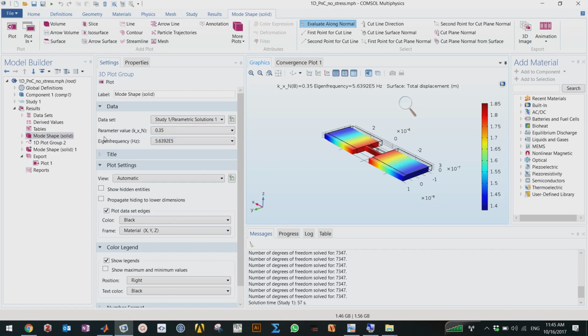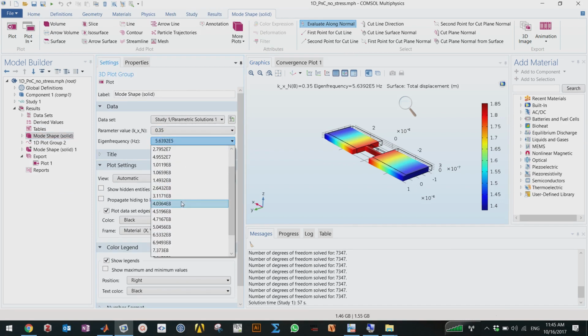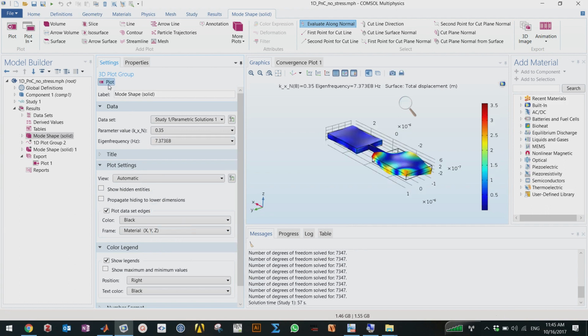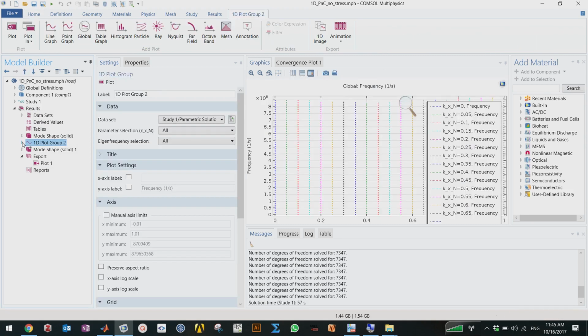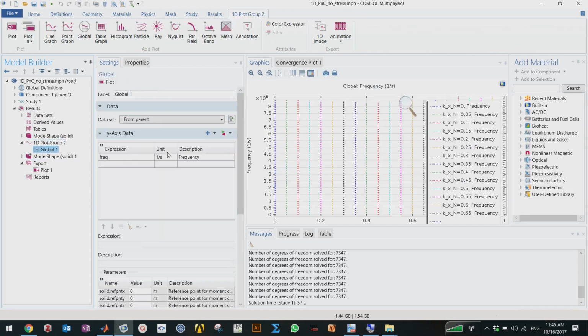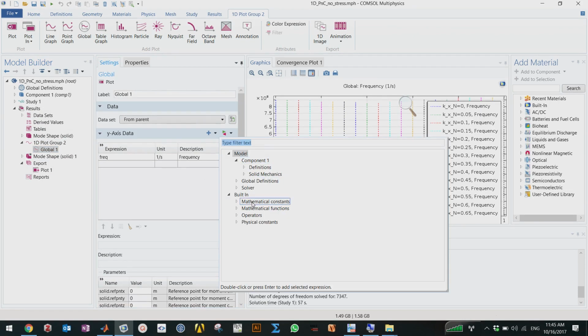So if you plot this, this will be your band diagram, but if you show this to anyone, they will be confused and say, okay, tell me what's going on here. So this is how COMSOL solves your structure. It just sweeps the k vector and then solves for eigenfrequency. So it has no idea what you want to do. So now the idea is to export this data, take it to MATLAB, and try to plot the modes to see the dispersion of different modes.